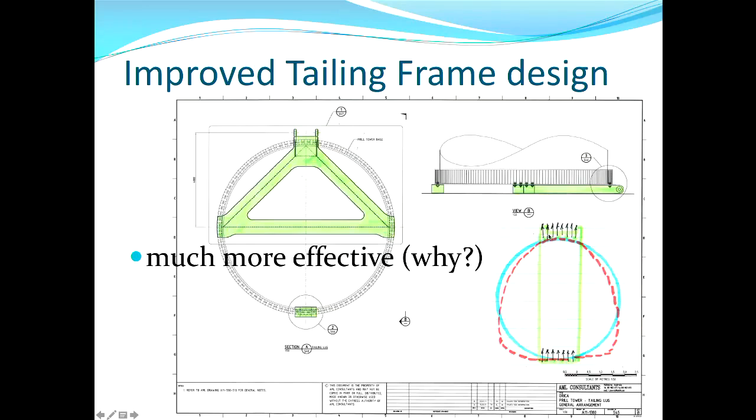because the shell of the prill tower up there and down there, those two, can you all see the pointer waving around there? Those distributed forces are really where the shell is very weak in terms of being able to transmit forces in a vertical direction. It's much stronger on the sides where the shell is basically vertical. So we, in the end, designed a different lifting lug that lifted the prill tower shell from the sides, not from the top and bottom, but from the sides, here and here.